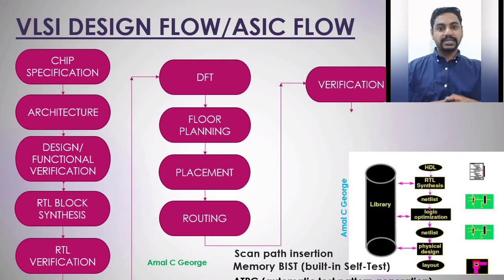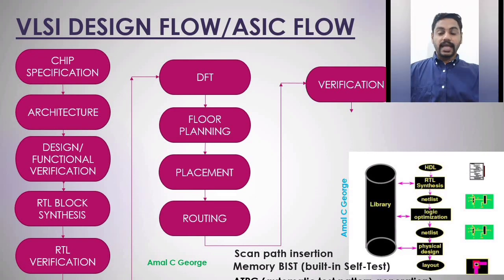runs different tester patterns. It is more difficult to debug in post-silicon validation than pre-silicon validation. It is because the level of visibility into the chip's internal nodes is drastically reduced in the case of post-silicon validation. A million clock cycles would have finished in a second, and tracing back to the exact time of errors will be a time-consuming process in post-silicon validation.